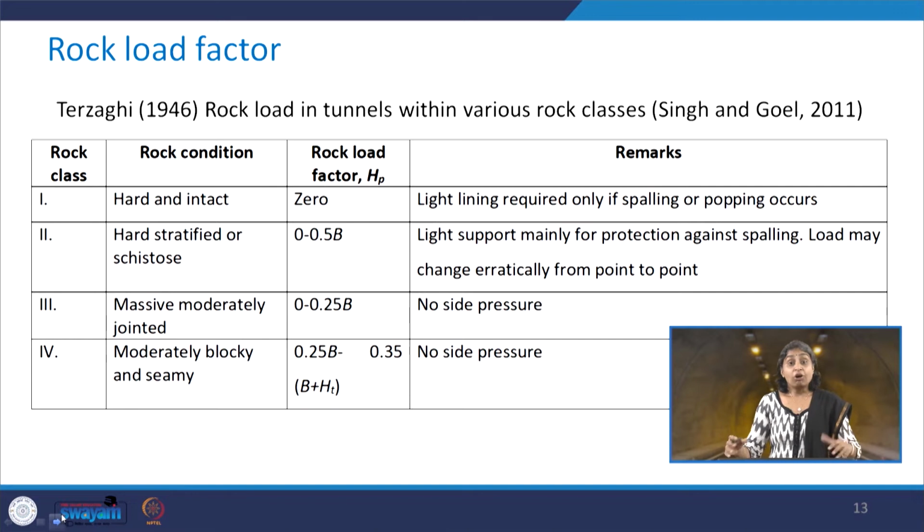So what should be the value of the rock load factor? Until and unless we know that, we will not be able to get the support pressure and will not be able to design the support system. This is what was given by Terzaghi: corresponding to each rock class, like 1, 2 up to the 11 rock classes, different values of rock load factors were defined.